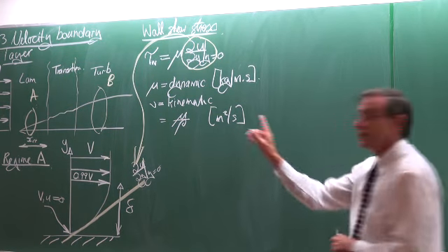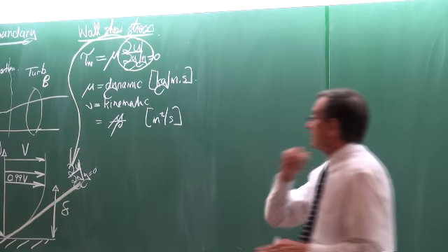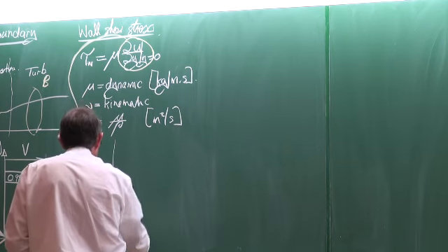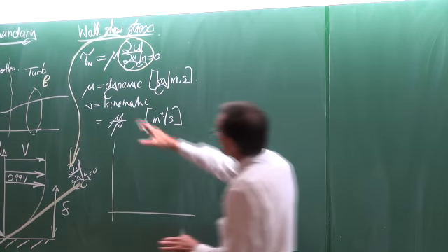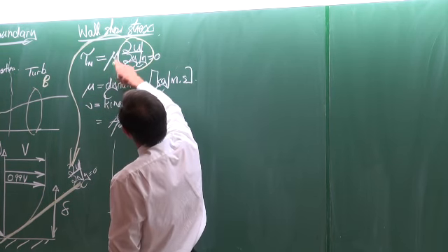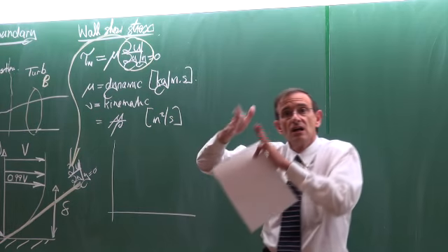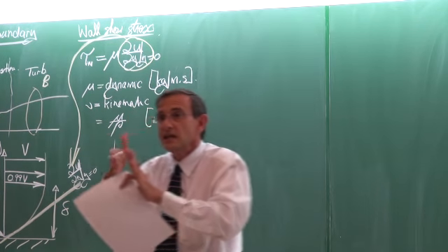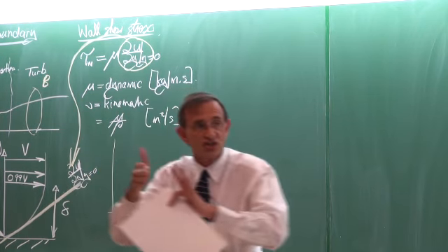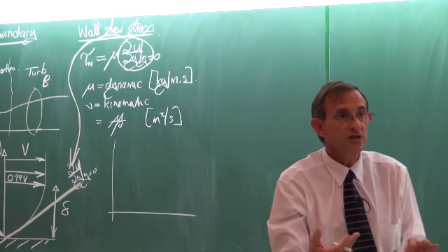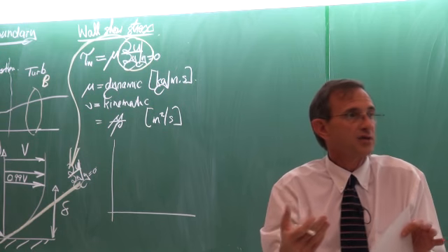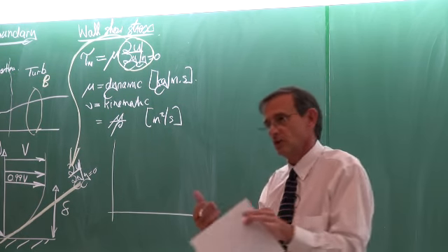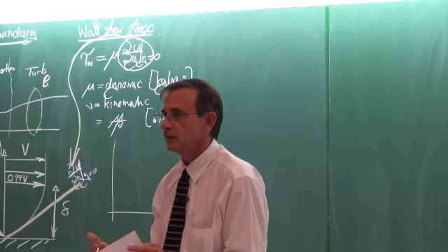Right. Now the viscosities are interesting. We know that there are two different types of relationships here. We have relationships where there's a linear relationship of the viscosity, which are called Newtonian fluids, and water and air and most of the fluids that we as engineers work with, fortunately, are Newtonian fluids.